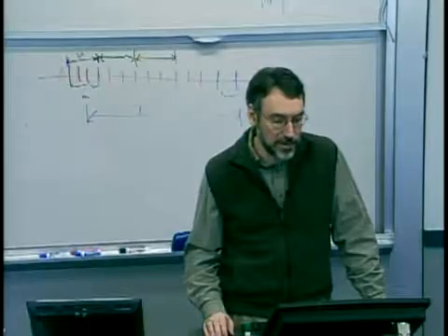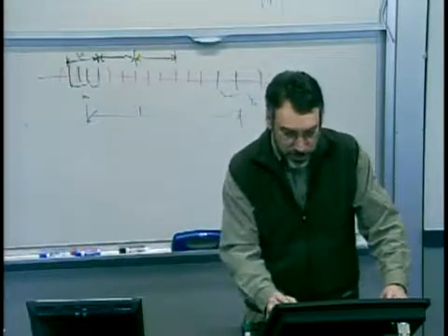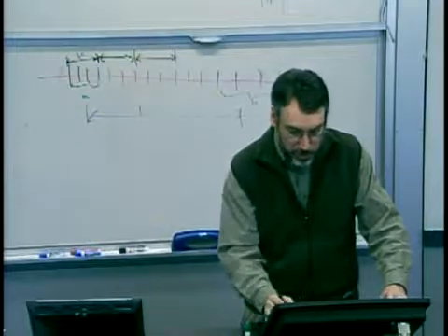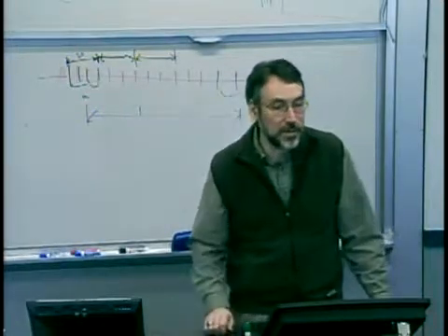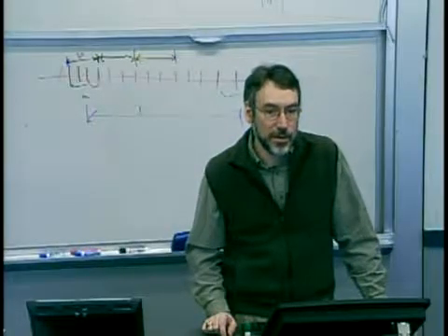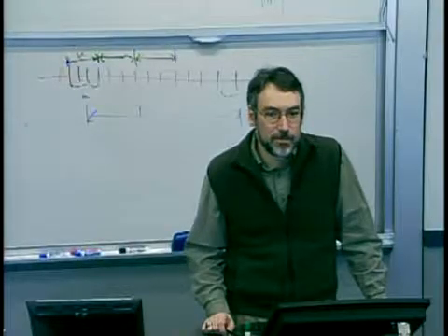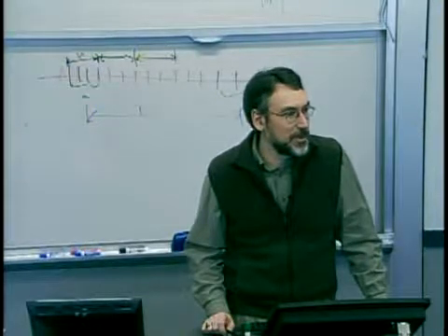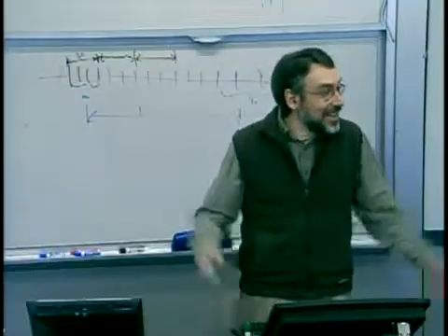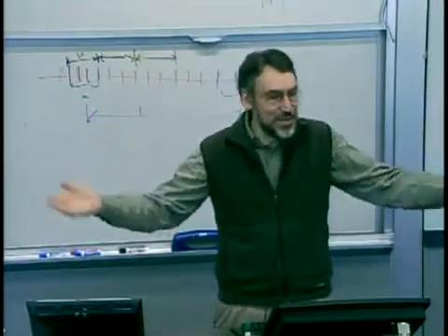Yeah, you'd calculate the mean and the standard deviation. First off, you have the true mean and the true control limits. Could you calculate a CP or CPK based on mean and standard deviation, if I give you those numbers? No, right? Because you need the upper and lower spec limits. Control chart by itself never gives you spec limits.